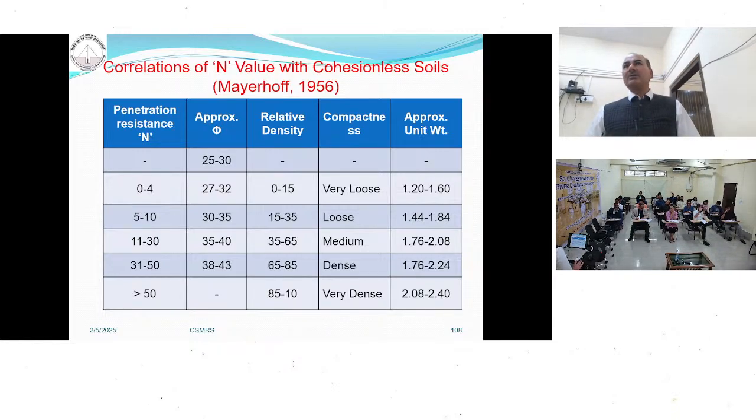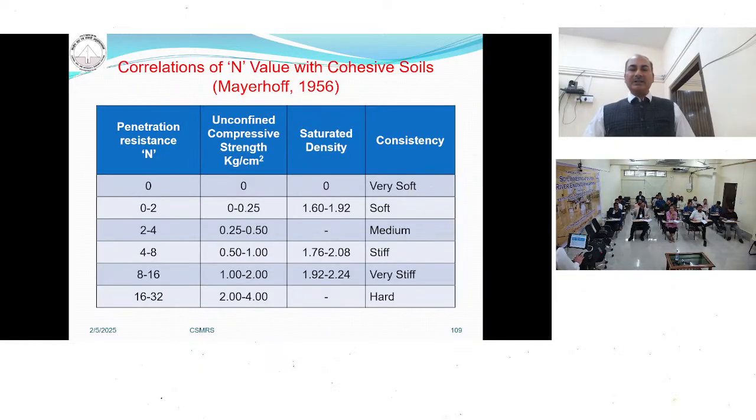When we talk about clay soil, where we conducted the SPT test, another correlation is given. Depending upon your SPT values or N values, you can say whether your strata is soft, medium, stiff, very stiff, or hard.